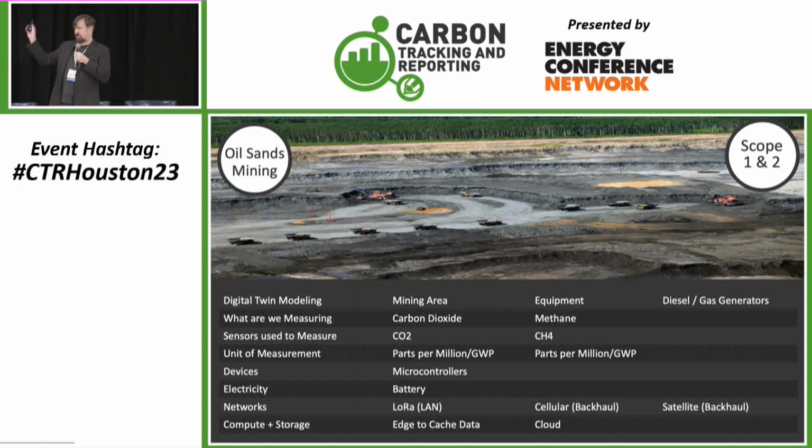Does anyone know what LoRa is? I'm just saying things, assuming too much. We all know what cellular is because you have a smartphone. There's a different kind of wireless connectivity that's super low power. It's just for sending little tiny bytes of data, maybe 50 bytes. I have lots of friends who work in that industry, and it doesn't use a lot of energy. So if you need to have a lot of devices in a place where you don't have electricity, you're probably going to use a low power microcontroller with low power sensors, and you'll use LoRa because you're not sending a lot of data. I'm just sending, every minute, every hour, every whatever.